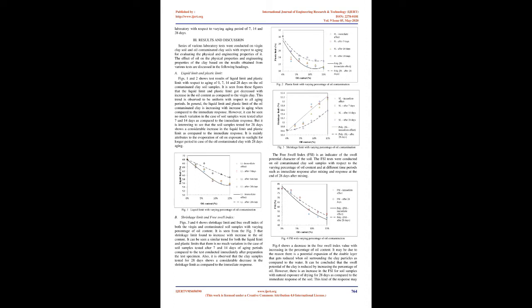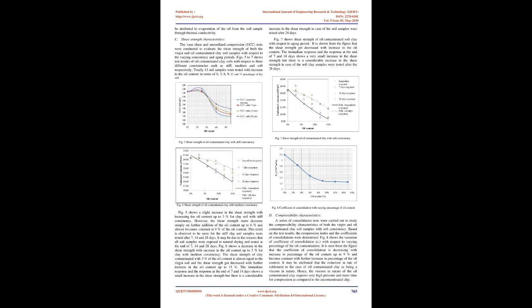In general, the liquid limit and plastic limit of the oil-contaminated clay increase with increase in aging when compared to the immediate response. However, it can be seen that there is not much variation in the case of soil samples tested after 7 and 14 days as compared to the immediate response. But it is interesting to see that the soil samples tested after 28 days show a considerable increase in the liquid limit and plastic limit as compared to the immediate response.